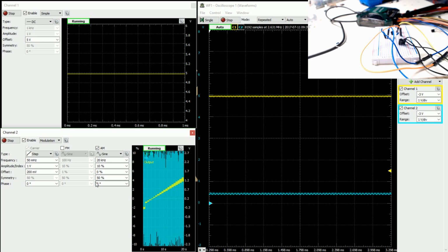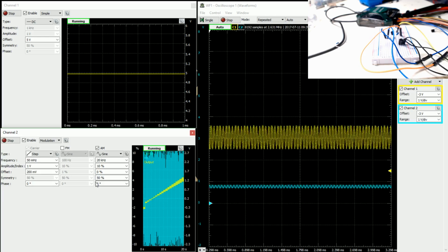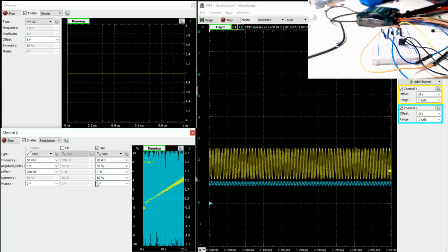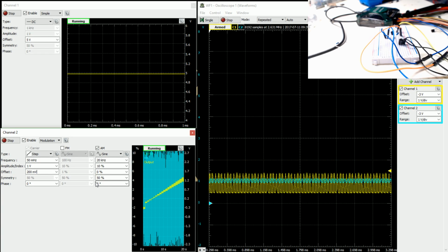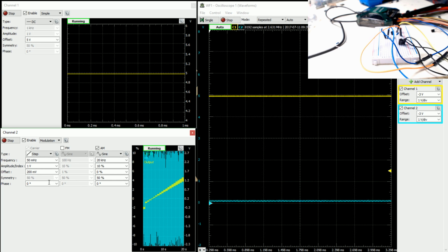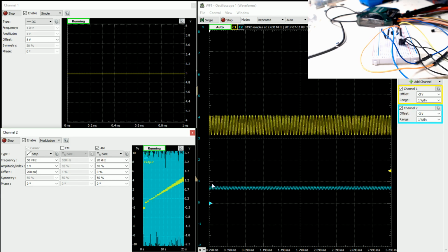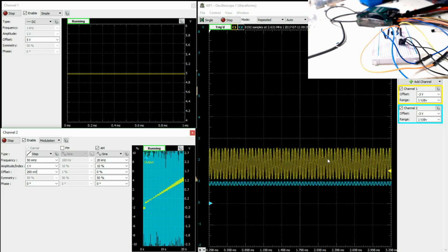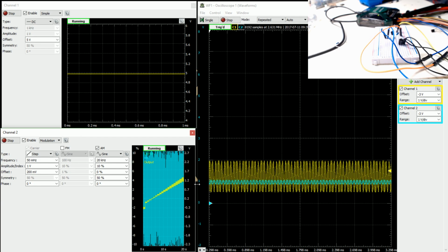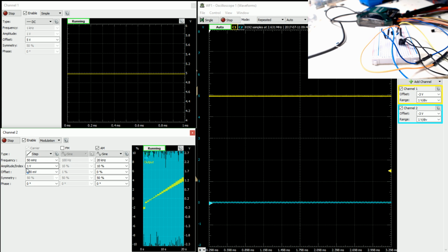What we should see is now that it's going a little bit higher, we should actually see that it overloads now that it gets past the 1 volt mark, right? So it's going to actually, yep. So now it's going a little bit past. Let's see now in this one, because it looks like it started a little bit lower last time. So you see the DC bias really isn't turning on that transistor at all. As it does start to get through, now it's turned on, right? We're still only going to 1 volt though. Let's take this up to 400 millivolts.